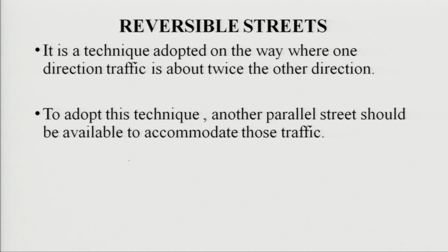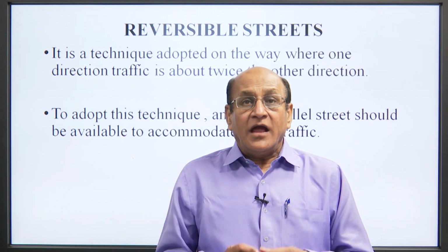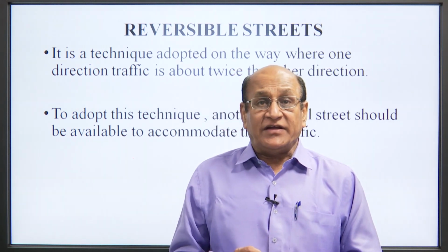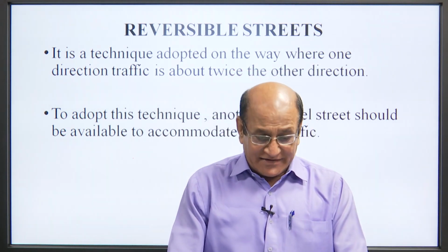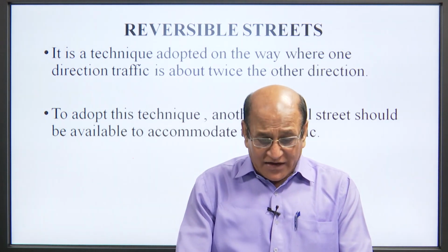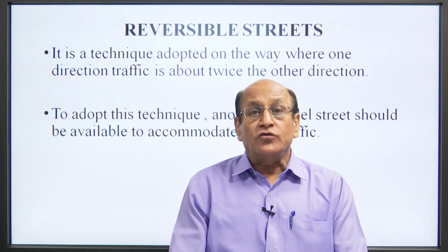Now, reversible street. It is a technique adopted on a way where traffic in one direction is about twice the other direction. To adopt this technique, another parallel street should be available to accommodate that traffic.